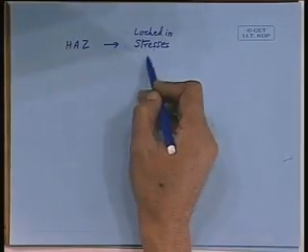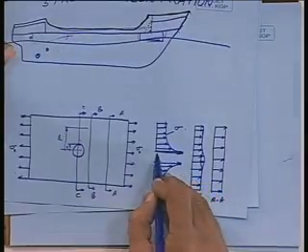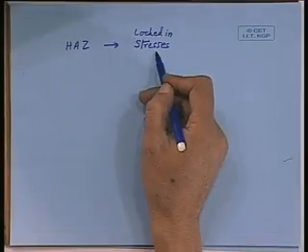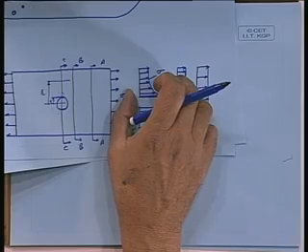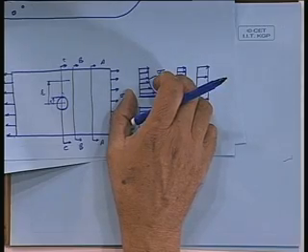So, we do not know the nature of this stress. If suppose we are talking about tension here and some tensile stress is already locked in, they will be additive here. So, if we are talking about 3 times this nominal stress here and some stress is already locked in, in practice it has been found that though theoretically we get a figure of 3 times the stress, sometimes you obtain 4.5 times the stress as the peak value.